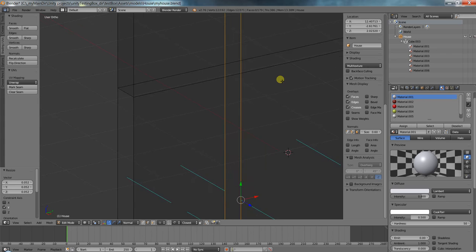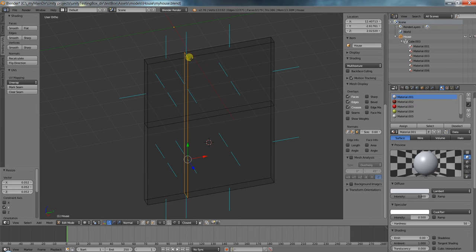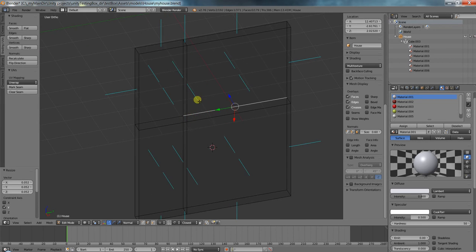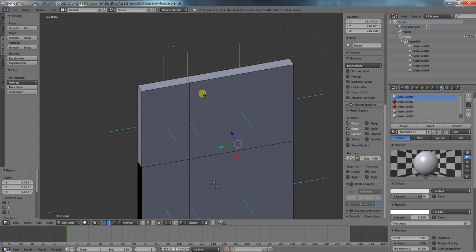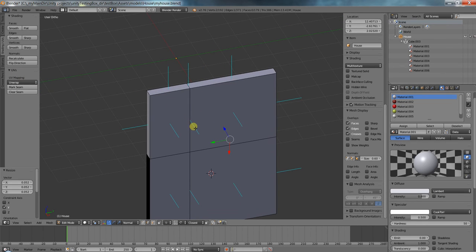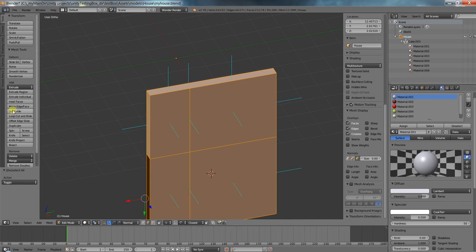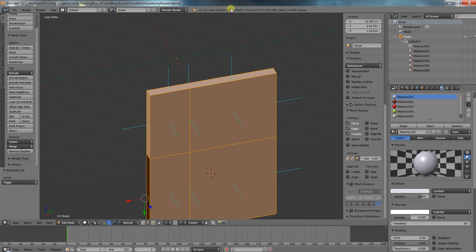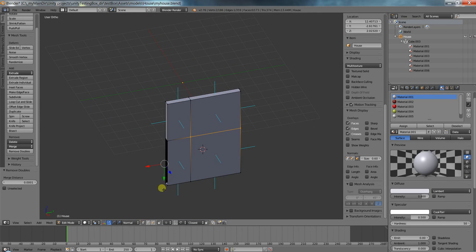But Blender does an extrapolation, which means that when vertices are that close to each other, it'll make one out of them. It'll merge them together. So in other words, if I select my entire wall and tell it to remove doubles, where's my remove doubles? You see that I have 24 vertices selected. If I remove doubles, I've removed 6. 1, 2, 3, 4, 5, 6. And now here I only have one vertex.